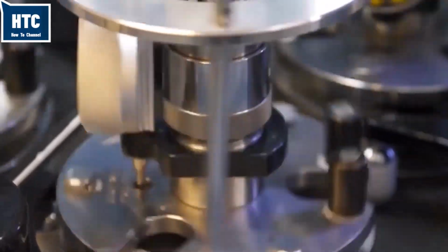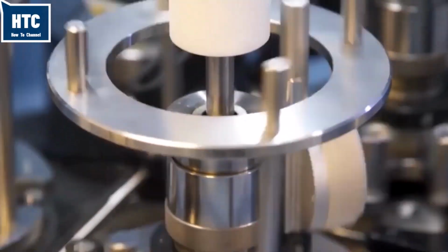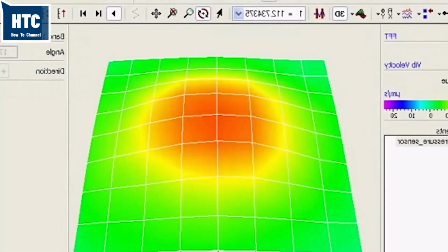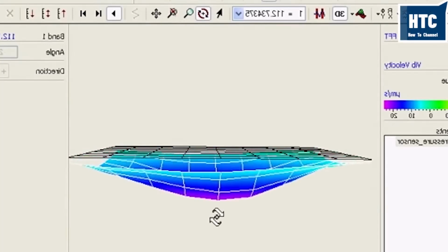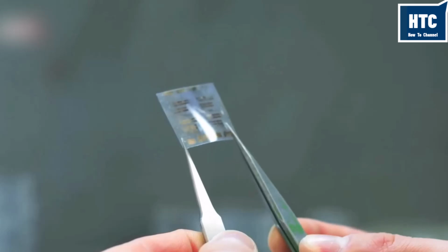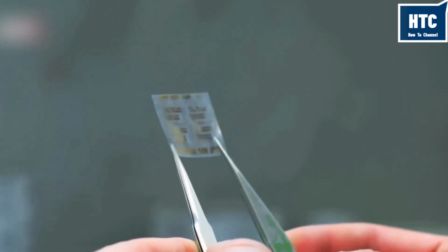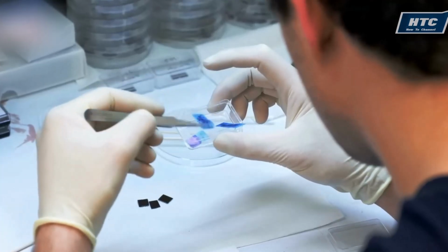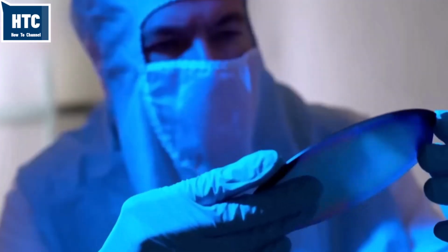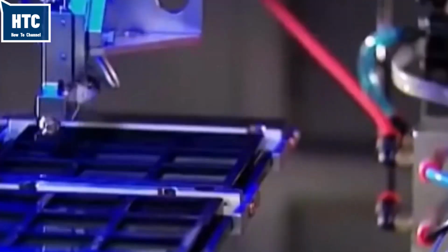The wafer is then mounted onto a sticky tape and sliced apart using a laser or a diamond saw. This is singulation. The bad chips are discarded. The good chips, the bare silicon dies, move to packaging. The silicon die is flipped over and attached to a PCB substrate. This substrate acts as an adapter, spreading the microscopic connections of the silicon out to the wider spacing of the motherboard socket. An underfill epoxy is injected between the die and the substrate to absorb physical stress.